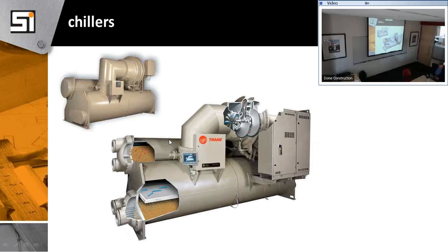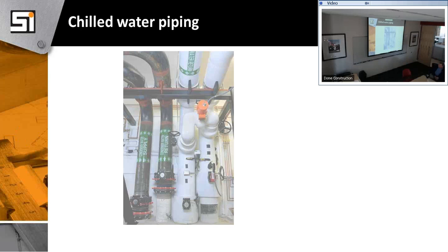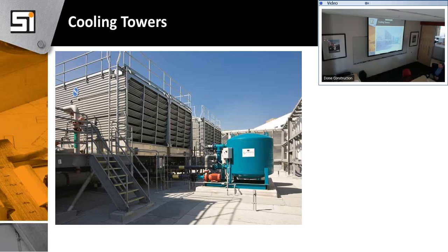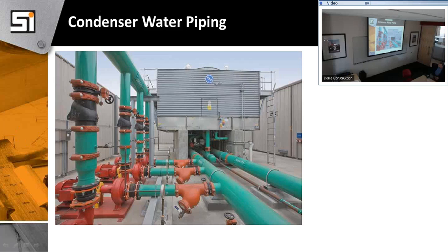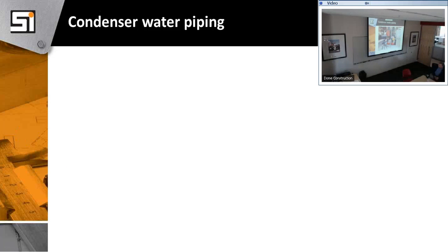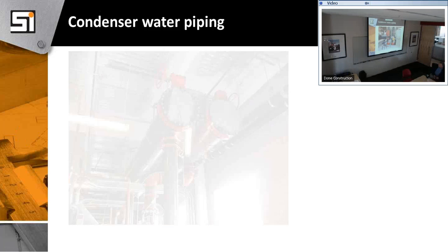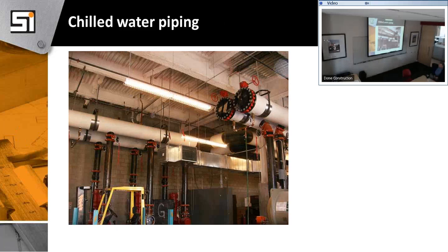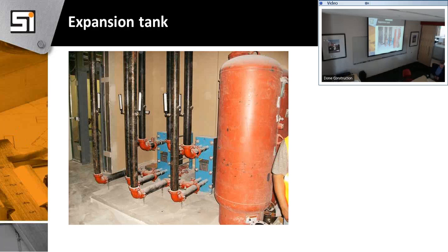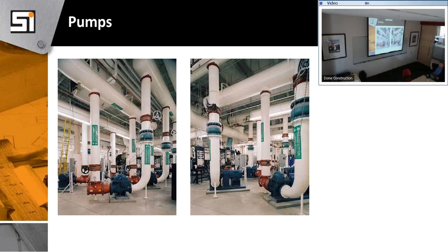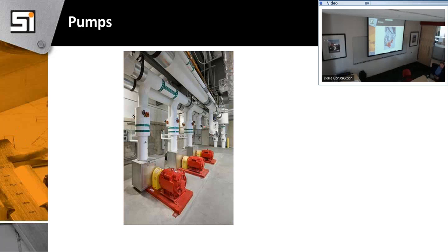So here's some water cooled equipment. Cooling towers, something you see, a big filtration system, a large tower system. Condenser water piping is uninsulated; insulated is chilled or hot. Do people know the difference between condenser and chilled water? You could say insulated or not.